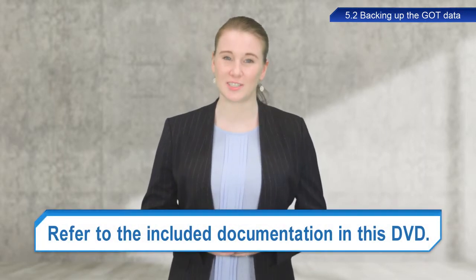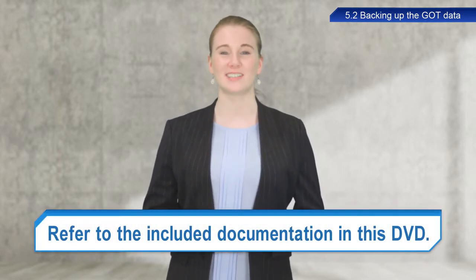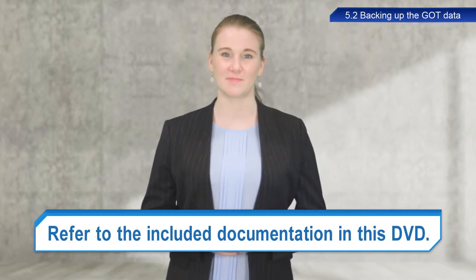A note of caution here. Before you can execute the backup utility, the backup and restore extension must be installed in the GOT's built-in flash memory. Refer to the included documentation for more information on the installation procedure. I will now describe the procedure to back up data stored in the GOT.